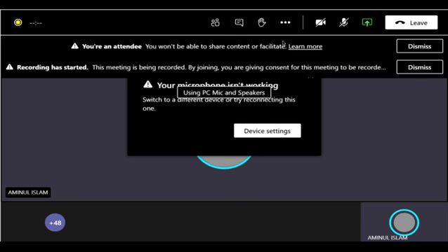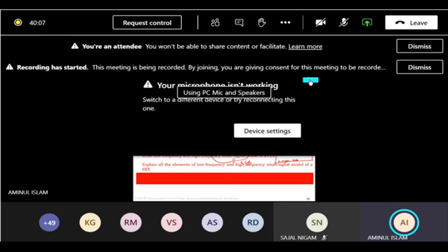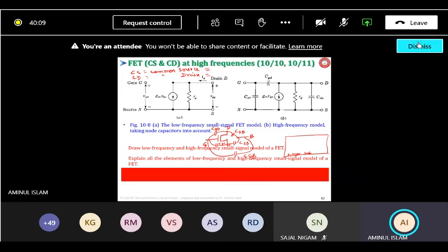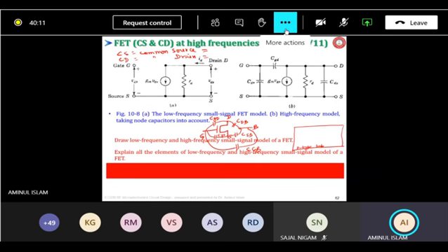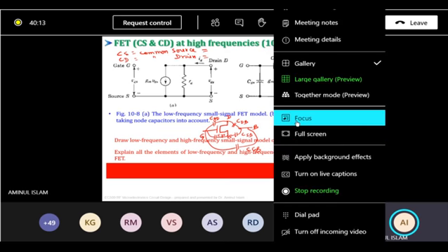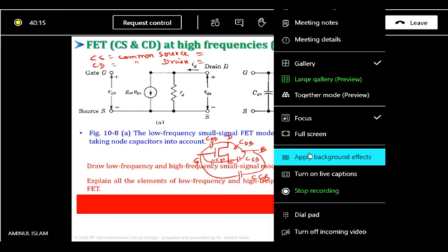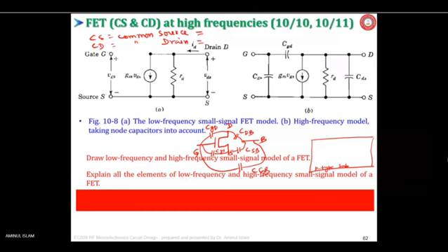And you want to make it P-type. What impurity will you add to it so that it becomes P-type? Can anybody say? Group 3 element. Such as? Boron. Good. So boron can be added to make it P-type. It has been doped and now it is P-type, on which you can make N MOSFETs directly, right?